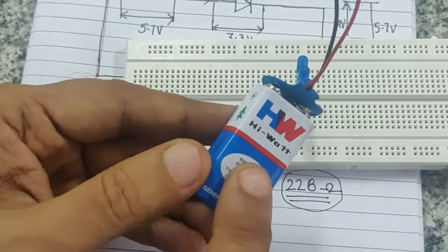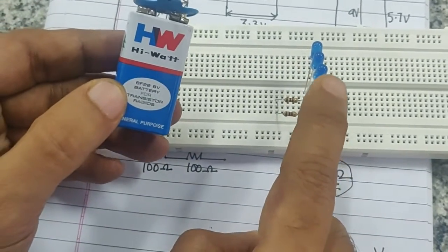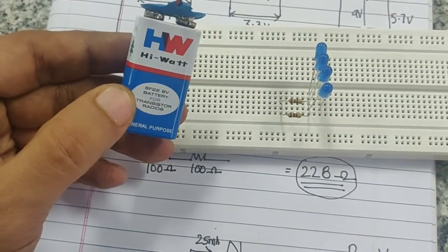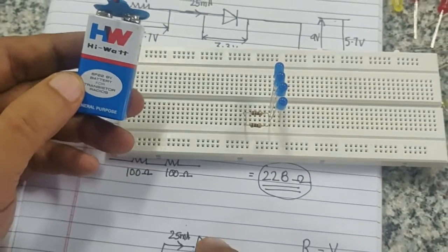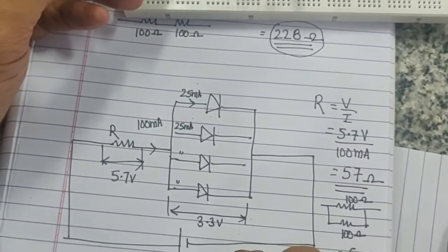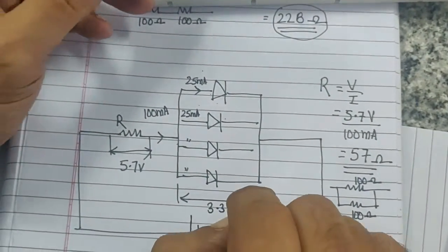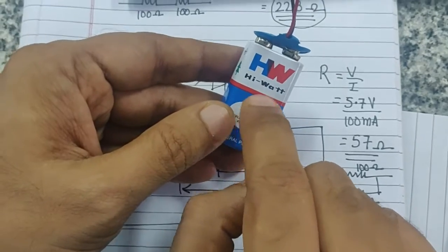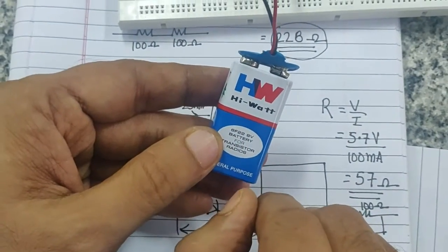Usually if you start drawing a lot of current from a battery, say 10 LEDs instead of 4, you draw 10 times 25, which is 250 milliamps. If you have 100 LEDs, that's 2500 milliamps. A battery typically has a limitation on how much current it can give.